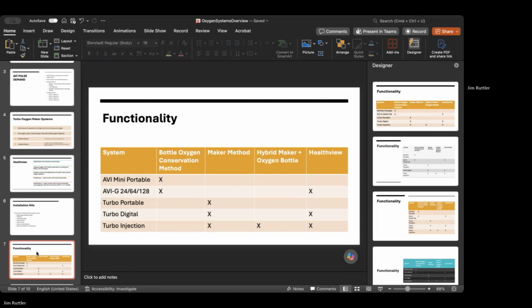Legal, Part 23, any AMP: both systems are equivalent. Any AMP can put it in as a minor alteration, does not require inspection authorization, and no Form 337. All right. Experimental, of course, there's no limitation.